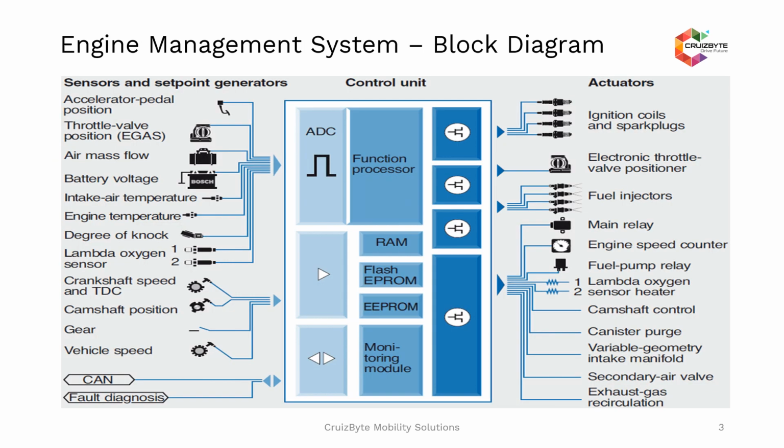This slide shows the engine management system ECU block diagram. On the left hand side you see n number of sensors present. On the right hand side you see n number of actuators present. Sensors are the key elements which produce values essential to provide necessary control to the actuators, and they act as set point generators for the software which is running inside the control unit.